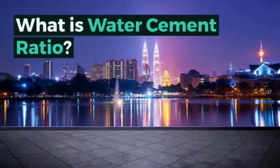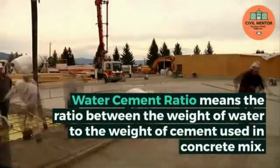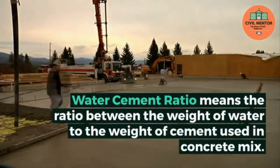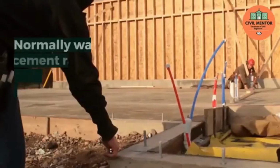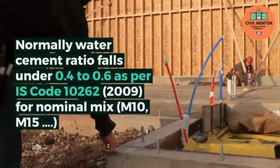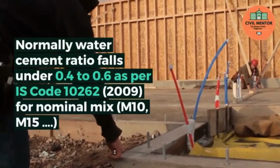What is water-cement ratio? Water-cement ratio means the ratio between the weight of water to the weight of cement used in concrete mix. Normally water-cement ratio falls under 0.4 to 0.6 as per IS code 10262, 2009, for nominal mix.